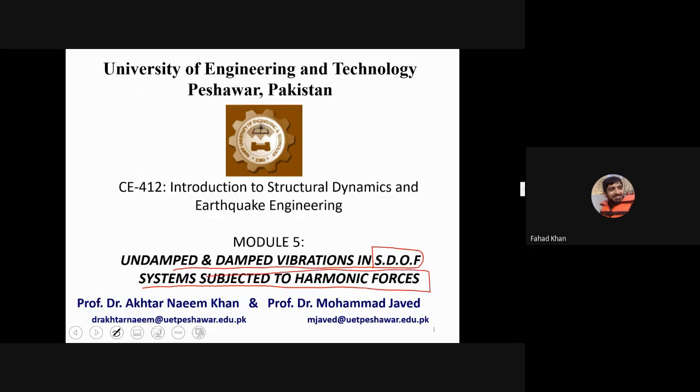So previously, if you guys remember, our equation of motion had taken this form: m u double dot plus k u is equal to 0, and we called this our homogeneous equation because there was no external force applied on the system. But right now we will be looking at this equation: m u double dot plus k u will be equal to some kind of external force, which is P of t.